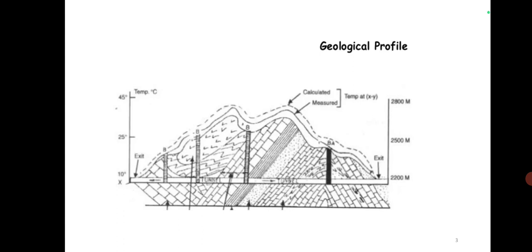Okay, so those values, even if it is limestone, if it is porous, then we can also do tunneling, but there can be a risk of caving in, or there can be water leakage inside the tunnel. So if it is meant for a particular purpose, then due to the leakage from above, certain sections of the tunnel may be unsafe, or it won't serve the purpose for which it was designed.